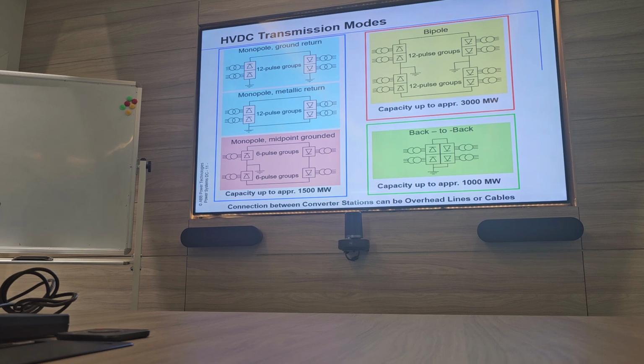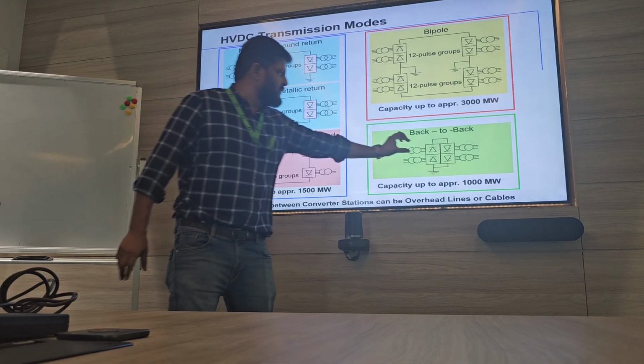The project in Saudi-Jordan is maybe 1,000 megawatt, connecting two AC phases back to back. Back to back normally is less than 1,000 megawatt. You can't transfer more. How about the distance? Then this converter station will be very big, right?